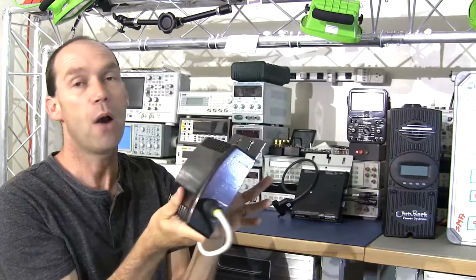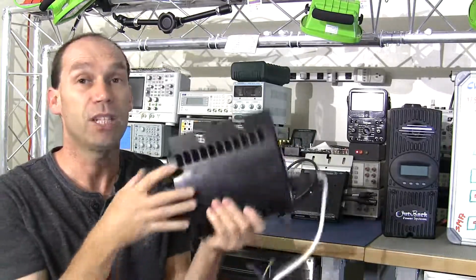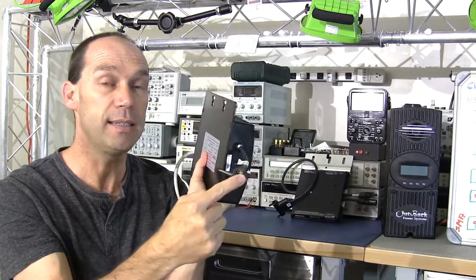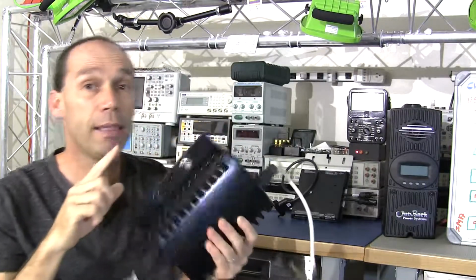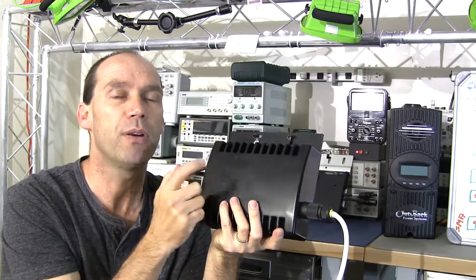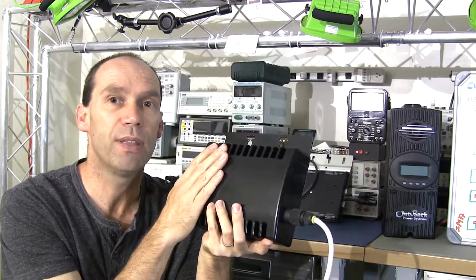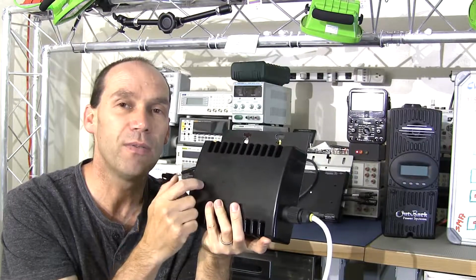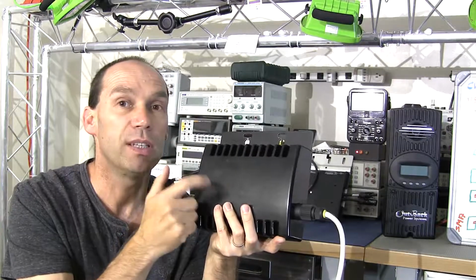A few years later I purchased this micro inverter, but this is a cheap Chinese inverter. It's actually fairly heavy, and it needs to be connected to the back of your solar panel. It then takes the DC from the solar panel and converts it directly to household AC. At the time, the interesting thing was I worked out that with these cheaper micro inverters, if I had, let's say, a 2,500 watt system and required 10 of these, the system would cost less than one big grid tie inverter, which was a fair outlay in cash.